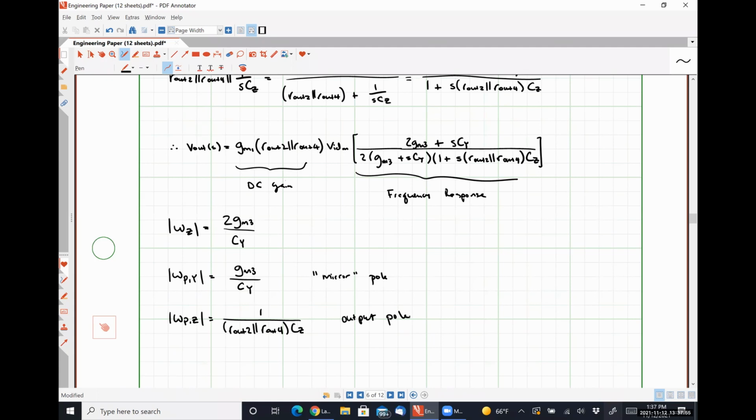And so we're going to do that by a technique called pole splitting, which is effectively where we force one of the poles very, very close to the origin, and we push the other pole so far out that we hit our 180-degree phase shift before the gain falls to zero. And so it's still technically unstable, but it'll be stable in a usable frequency range. So effectively, we're forcing it to be stable until we hit the gain bandwidth product. And then after that, who cares? Because it's not usable as an amplifier anyway. So that's what we're going to talk about on Monday.